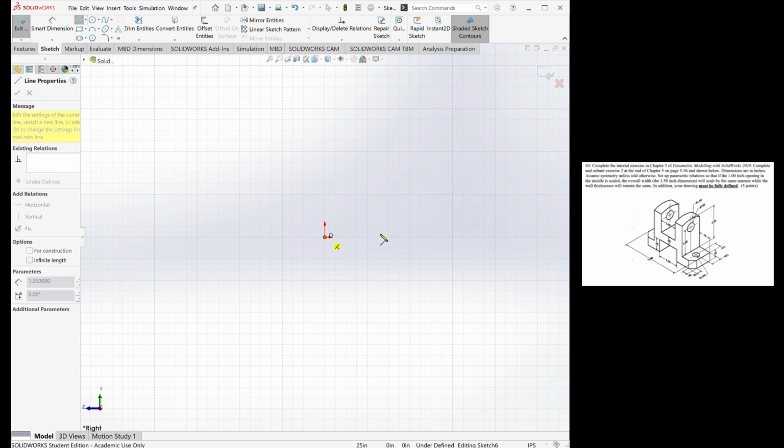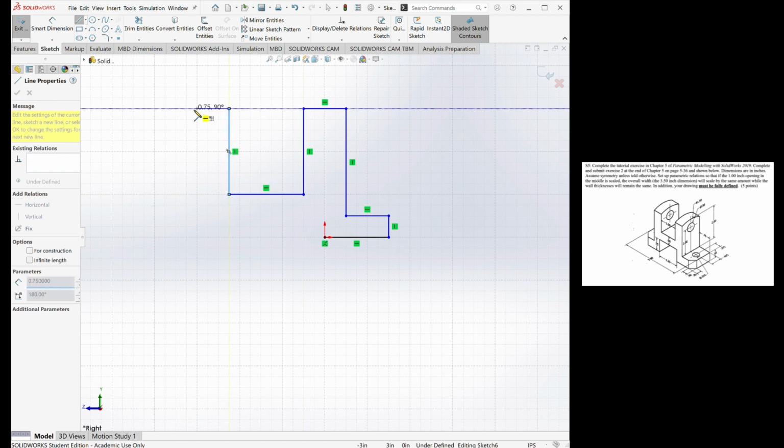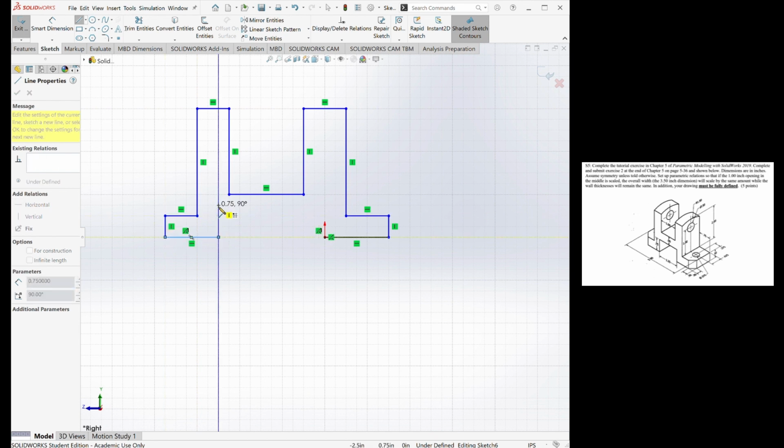All right. So we're going to start out by making a sketch as always, and on that sketch, we're going to make the back face of the part. We're going to ignore the little rounded top parts. We're going to get back to them later. But this is very important that you start out the sketch with the origin on one side. It should not be in the middle. Where I started out with it in that little corner there is a spot that I would obviously recommend.